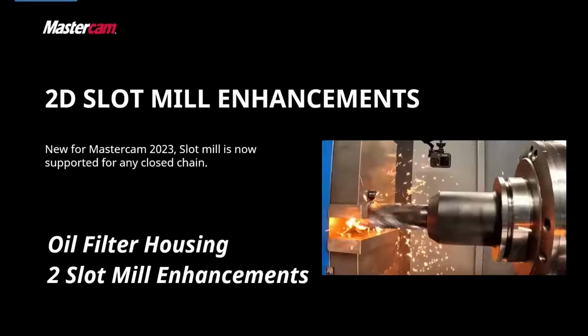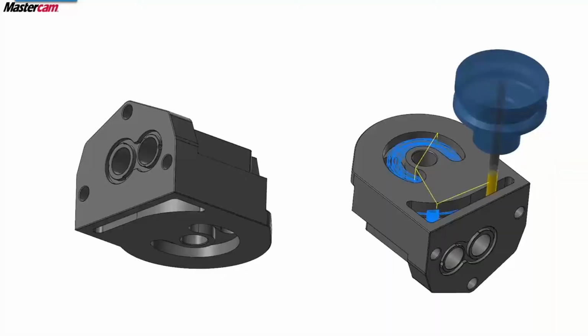Let's talk about 2D slot mill enhancements. So now, able to do some interesting shapes, not just the straight on slot. Before, you would have to have two parallel sides and a closed chain to get in and use slot mill. Now we're able to do some more interesting shapes, as you can see in the graphic here. We've got some circular slots, and we have this weird pocket down here on the bottom. Pretty cool.